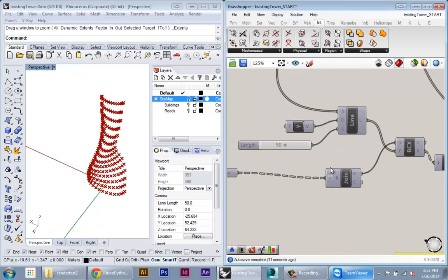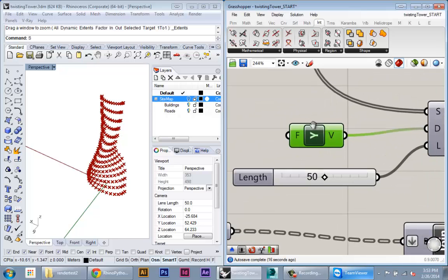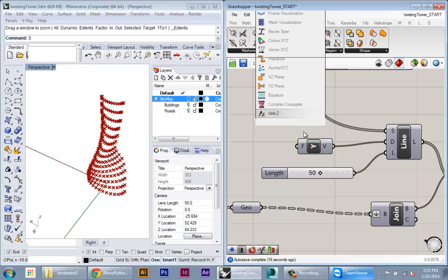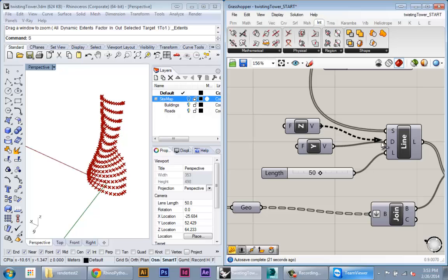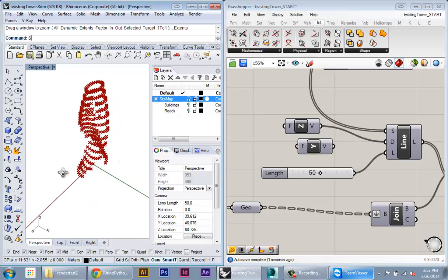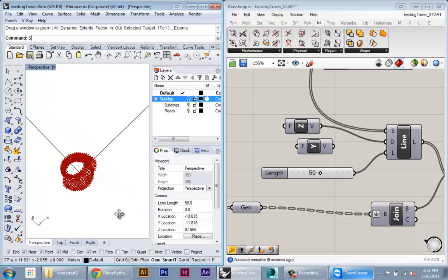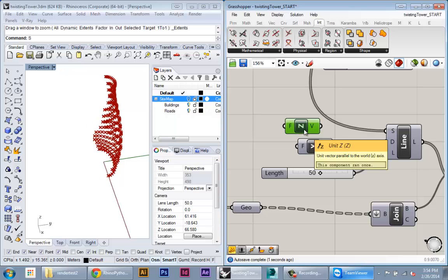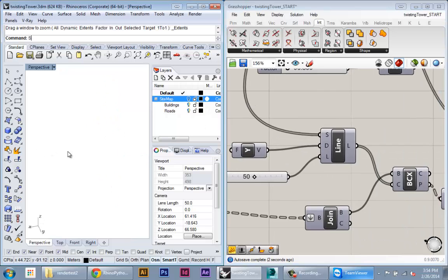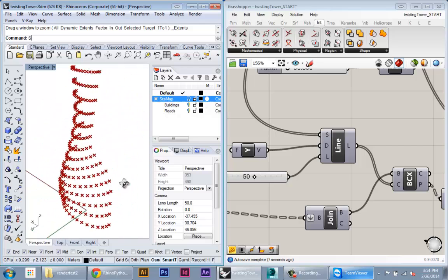This is set up so you can pass any vector. Here I have the y vector. I can also use a unit z vector as my direction. It'll give me only the points that are visible from the z direction. But you can use any direction. So if you're doing wind load, you can feed in the primary wind direction into here.